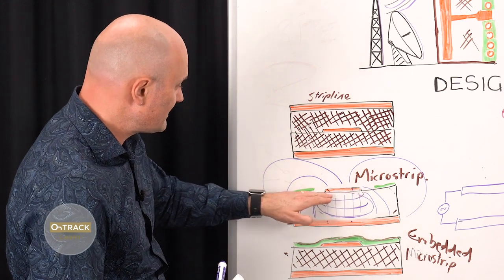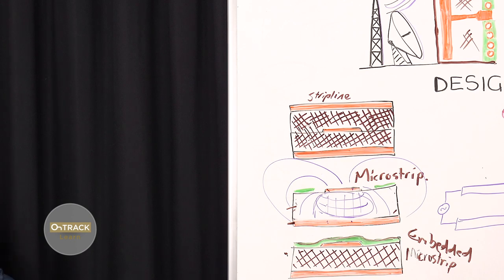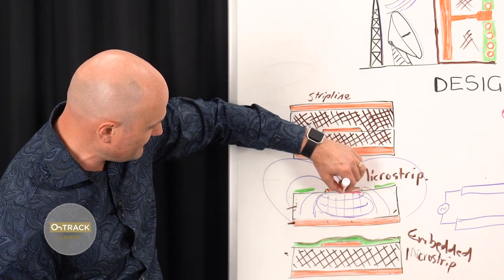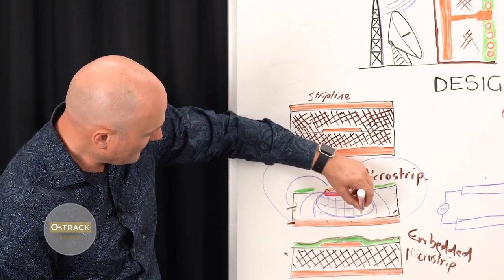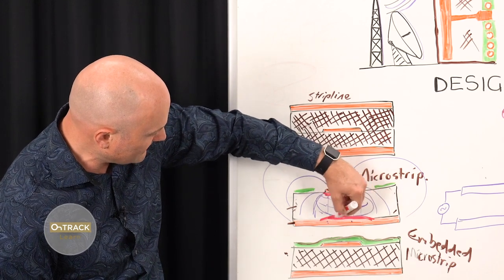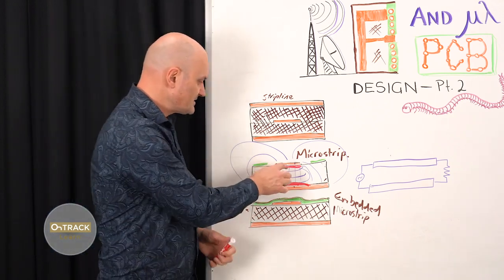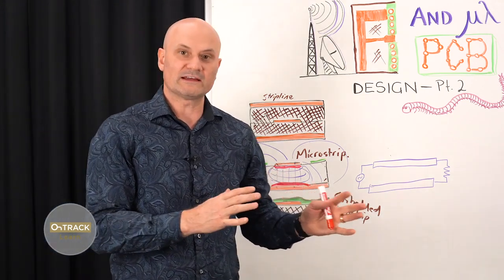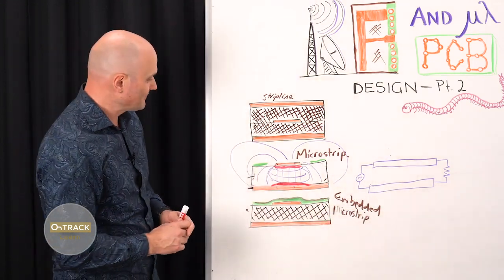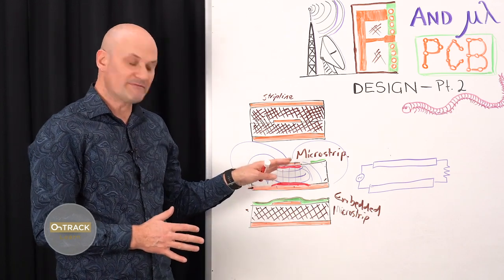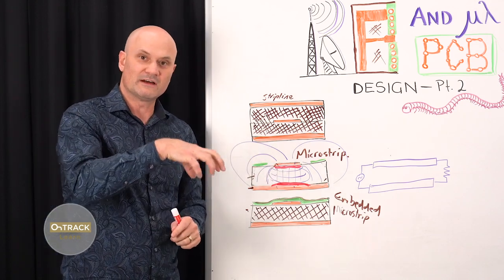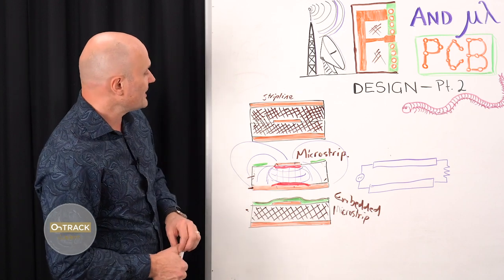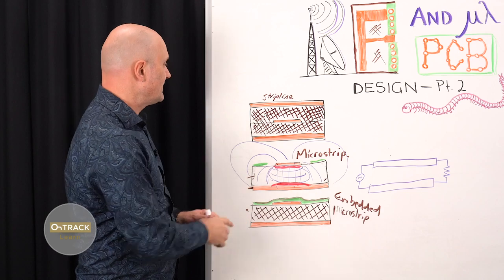And because this is the area where the coupling is, most of the RF and high frequency currents are traveling in the skin effect in this region right here. The return path currents likewise are mostly traveling in this region of the plane. Because of that, it's actually a very tiny area of the bottom surface of the conductor that's got the electrons moving back and forth at high frequency AC. When a printed circuit board is manufactured, this area of the copper is typically what's made rough for attachment, as we discussed. And that means this is where we have increased losses.